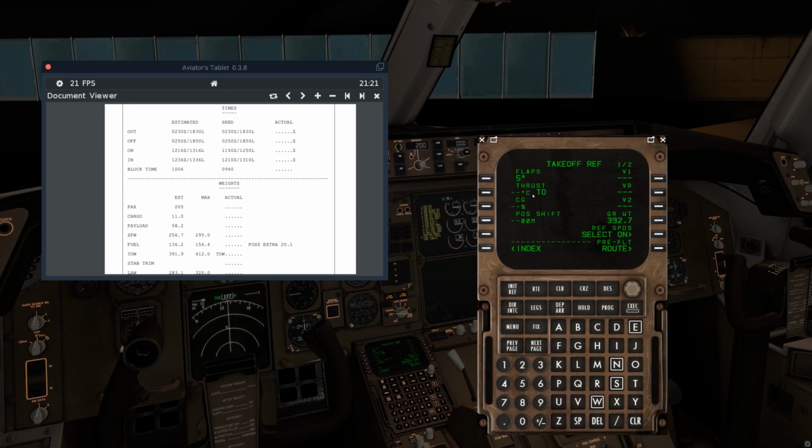Your actual thrust rating, you normally will do a D rate, and it's based on an assumed temperature, or a flex temperature in Airbuses. So what you do is you take the actual temperature outside, which if we look right now, is 5 degrees. The total air temperature, we're not moving, so the static air temperature and total air temperature are the same. So it's 5 degrees out.